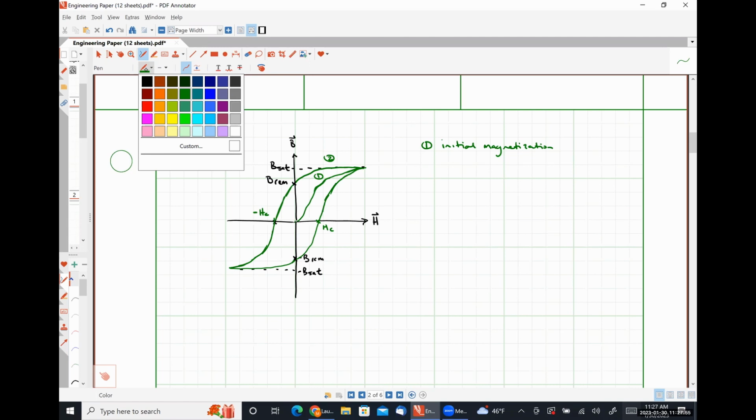And so there are things called magnetostrictive drives, which effectively you wrap a coil around a material and then you just pulse current through the coil, and it causes the material to slightly expand, contract, slightly expand, contract, and you get this inchworm-like movement or actuation of the material inside the coil. Okay. I haven't been able to find anything about that being used in MEMS devices, but I thought it was very interesting and I learned something new. So I figured I'd tell you guys about it. It's a pretty neat actuation scheme. So anyway.